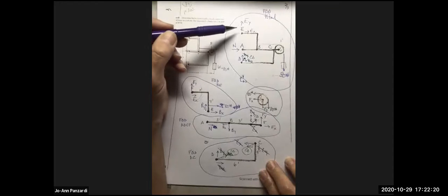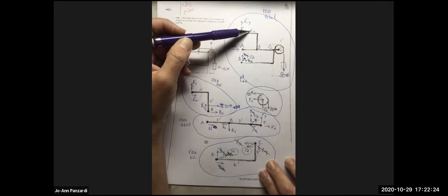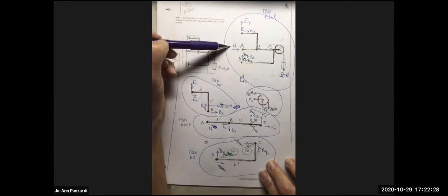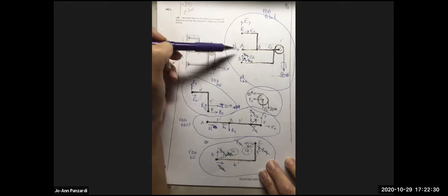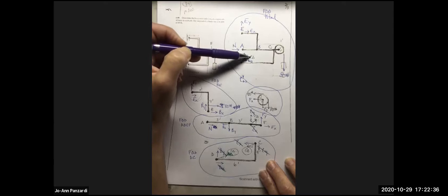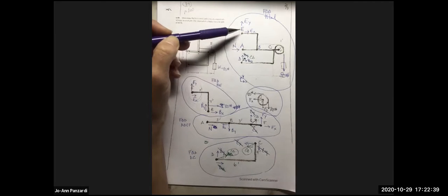We could do some of the forces in X and Y, and then we could do some of the moments. Okay, hang on. The sum of the forces in X will give me EX and the X component of CD, so that's 3 unknowns in that equation. The sum of the forces in Y will give me CDY and EY.